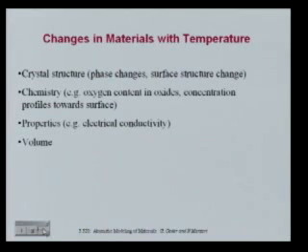So most people who work with ceramics know that if you heat them high enough, they start reducing. So they start losing oxygen. This is one of those things where it's an obvious temperature effect. Properties, there are obvious properties, electrical conductivity, thermal conductivity, all these things are very temperature dependent. In some cases they have trivial forms at low temperature. And then there are sort of trivial properties, volume. Maybe you want to know what the thermal expansion does. So I'll go through several of these.